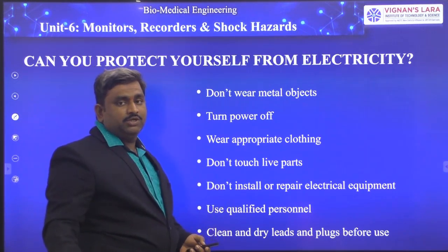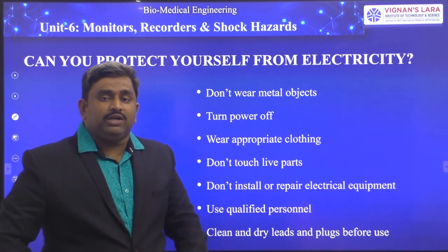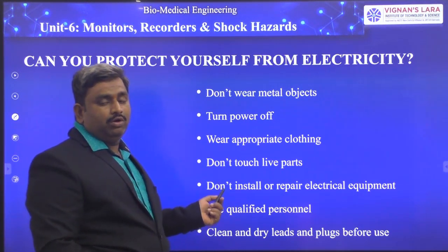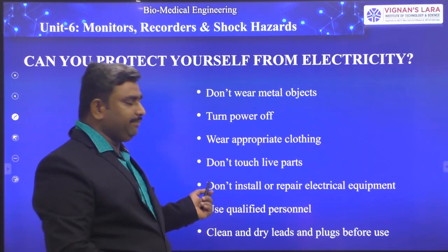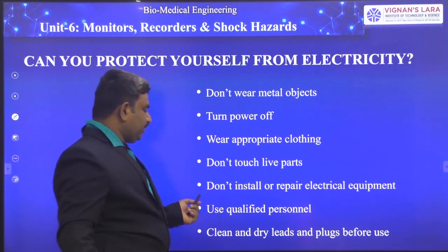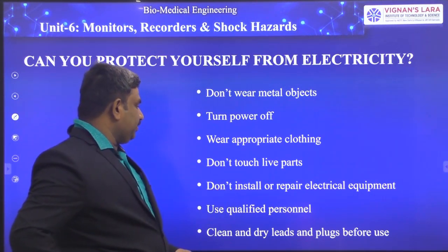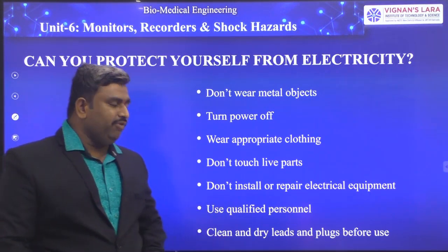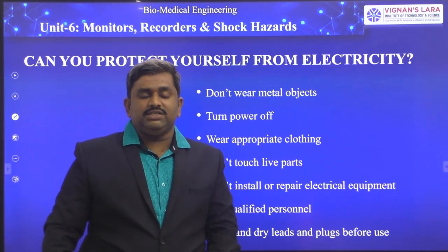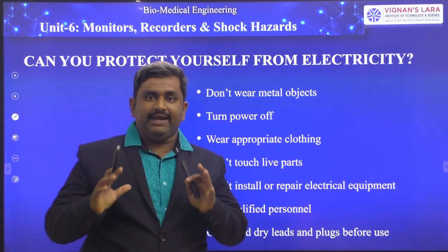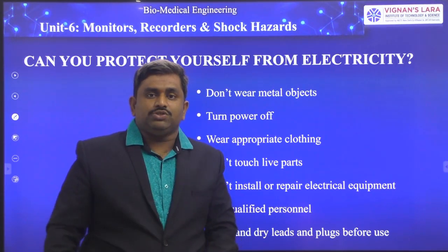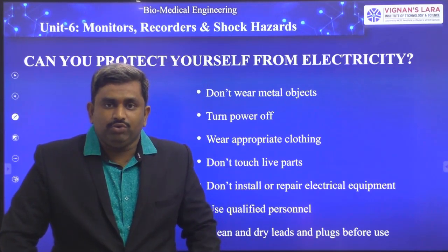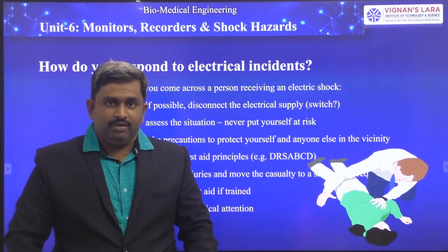Don't touch the live parts. Wherever the current is available, we don't have to touch those live parts. If you touch, automatically you will get an electrical accident. Don't install or repair electrical equipment; use qualified personnel. Clean and dry leads and plugs before you use them. In many cases, wet hands or wet areas may cause electrical accidents. So first we have to clean everything, and then use it properly in a perfect way.